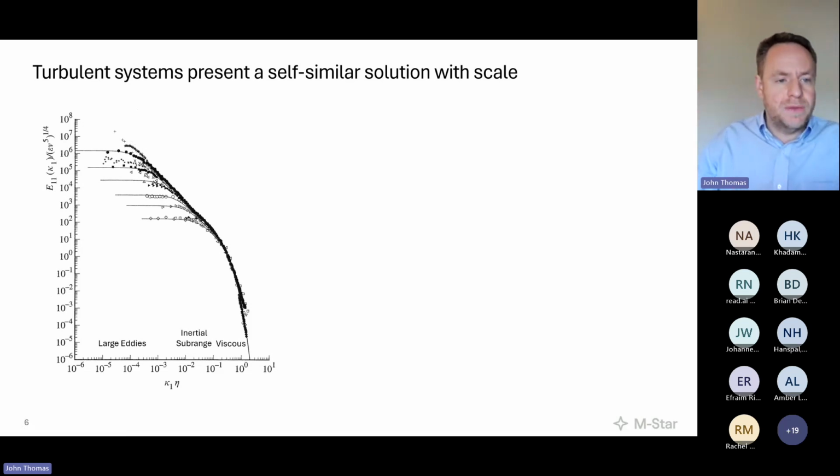Of course. But if we divide this by the total energy, we get this beautiful self-similar curve that describes how energy will be distributed from this inertial subrange down to the viscous regime. And that's where Kolmogorov and Taylor start to win. That is all the turbulent structure. Integral scale is different, but in the limit of the isotropic turbulence, it converges down to a self-similar solution.